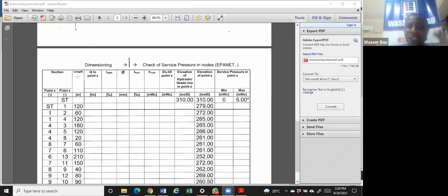So those 4 parameters, 1 has been achieved. So if the surveyor gives you his data or it has been plotted on a layout, it's easy for you to know the diameter, the distances, because you can easily use your mouse, use your inquiry tools on AutoCAD, and you mark them out. That is so simple. After that, what do you do?